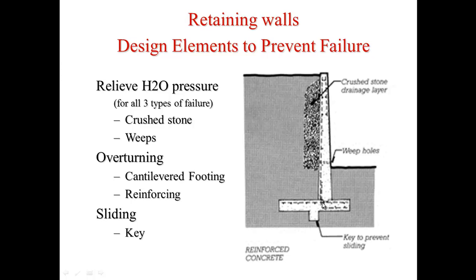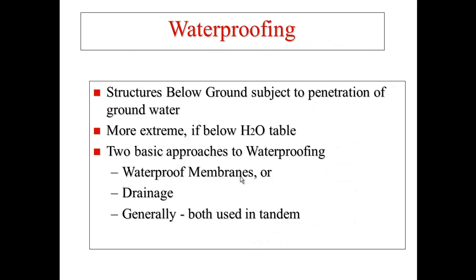So generally you put a 2x4, or a 3.5 by 1.5 2x4, in the footing, remove that, and then pour on top of it, so this key keeps it from sliding sideways. All good methods for maintaining a good retaining wall.